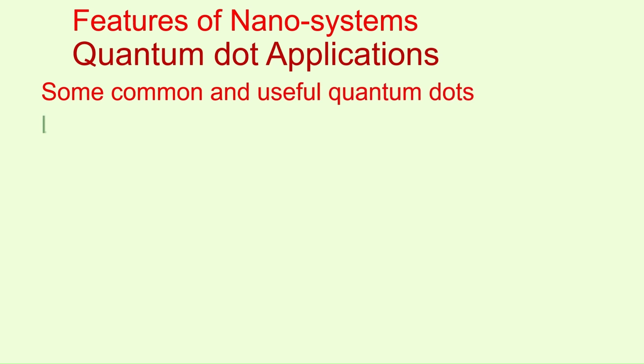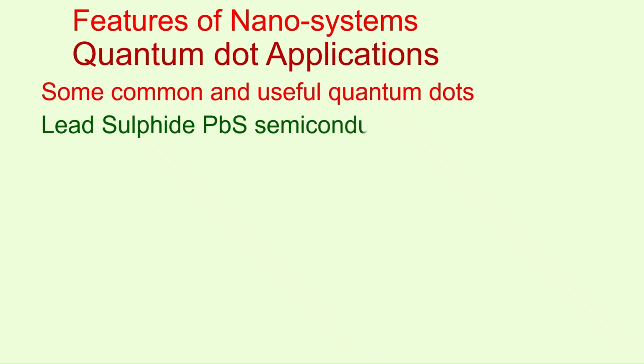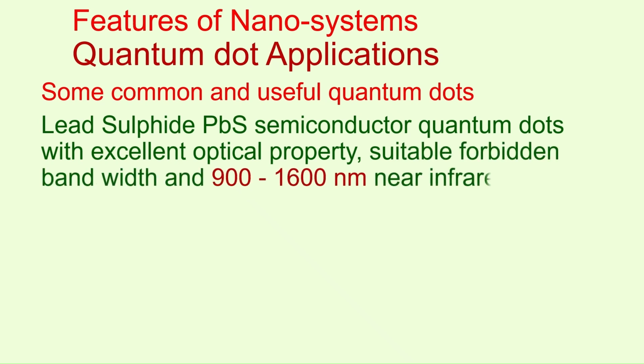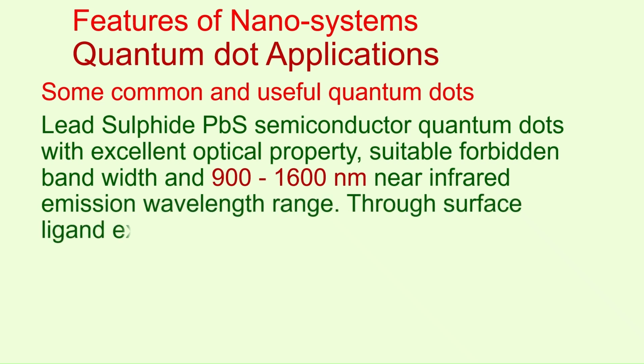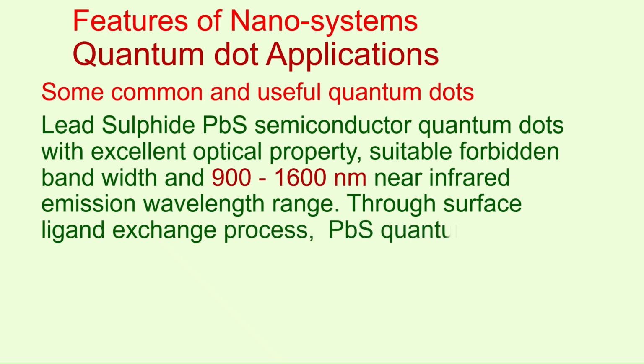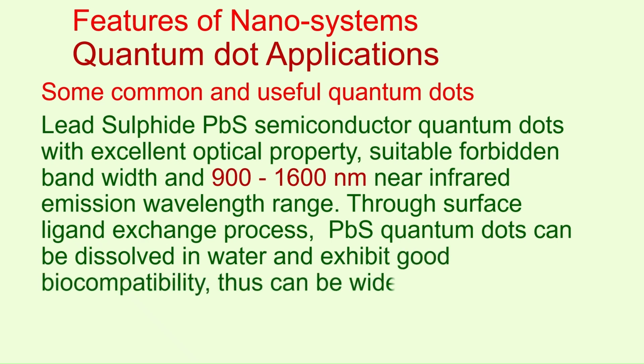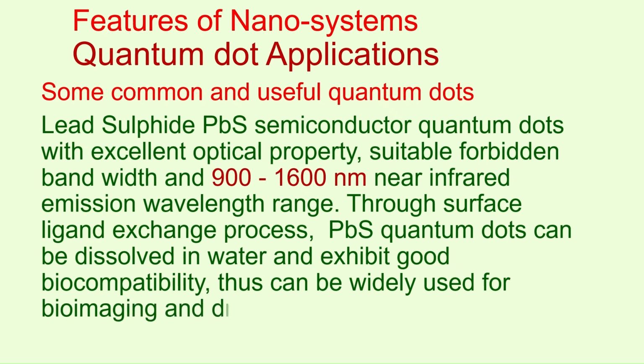Another very useful quantum dot is lead sulfide, PbS, semiconductor quantum dots, which have excellent optical property, suitable for forbidden bandwidth and 900 to 1600 nanometers near-infrared emission wavelength range, through surface ligand exchange process. PbS quantum dots can be dissolved in water and exhibit good biocompatibility, thus can be widely used for bioimaging and drug delivery.